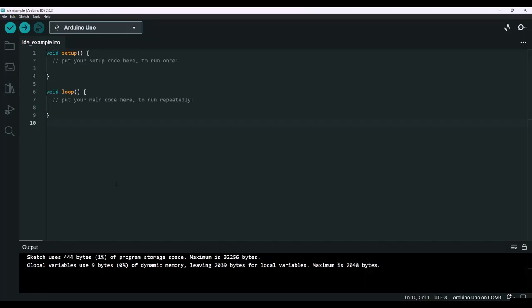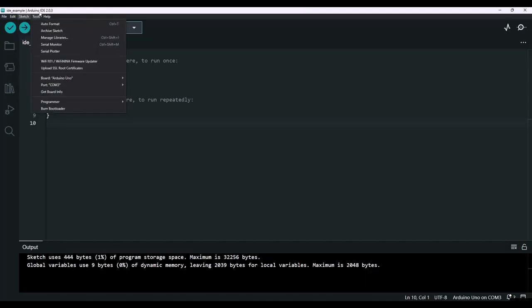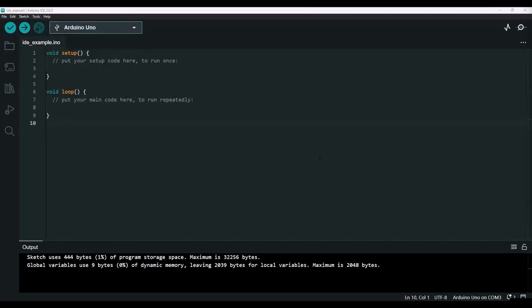If you just see a number in the COM ports, so if we go here and you just see COM3 and COM4 and COM5 or something like that, you may have to do a little bit of trial and error to find the right one. You'll know you've found the right COM port once you can upload the code successfully. And that's it. You now have your computer set up to start the course.